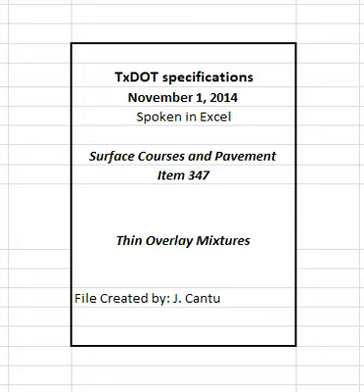4.9.2.3 Production testing. The contractor and engineer must perform production tests in accordance with Table 10. The contractor has the option to verify the engineer's test results on split samples provided by the engineer. Determine compliance with operational tolerances listed in Table 8 for all sublots.